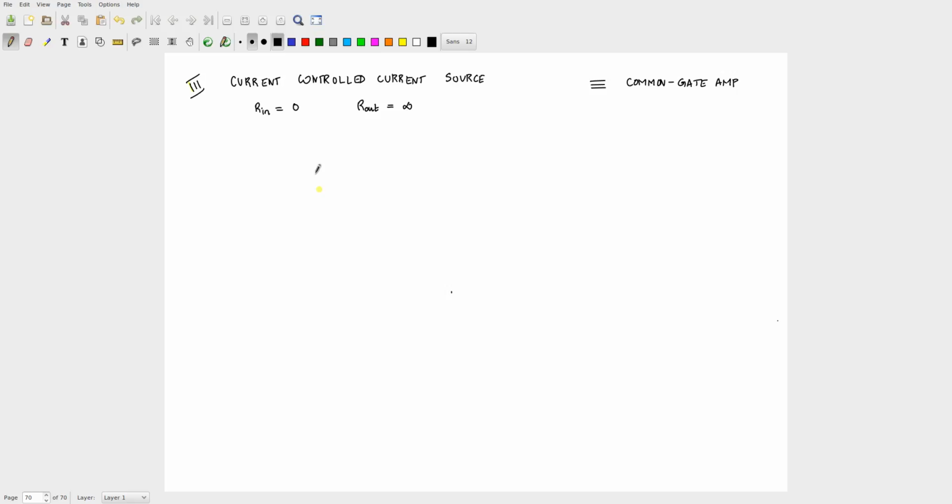Alright. So if we want to make this, again, verbalize how you would do this. I have an input, so basically a current controlled current source. I want this, and let me also say that I want a gain of 1, so that it simplifies matters, a gain of unity. Which means, what is the kind of circuit we are looking for?